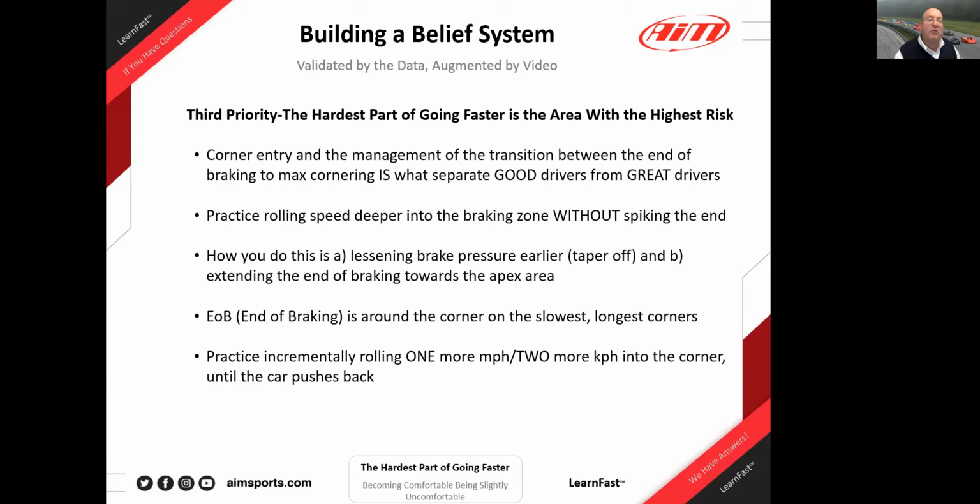Dion von Moltke, Racers 360, was one of the first people that I heard verbalize this the correct way, which is we want to finish the braking at the point where we want to be going the very slowest, which is at a point where we can go back to power and continuously and progressively apply throttle to wide open.